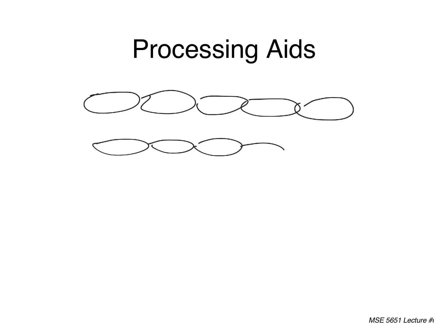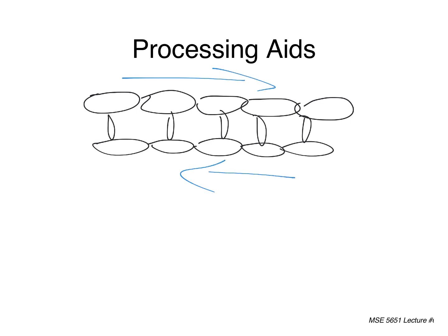So if I go back to that one example of particulates held together by other particulates, and I start to try to shear this thing, we can look at this in a couple of different ways. The first thing that would break under shear are the bonds that hold these two chains together, because it's easiest to do. All right, that should make some sense. Afterwards, if we keep shearing it, we want to break down our viscosity, then we start breaking the bonds that exist between the linear structures themselves.